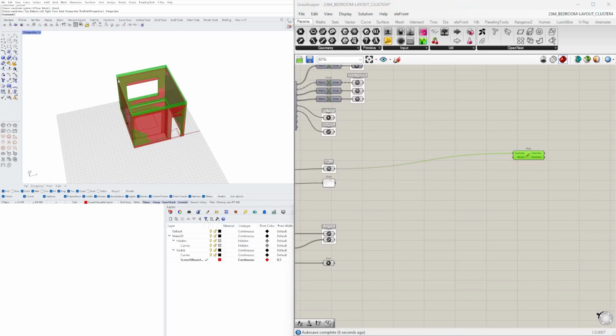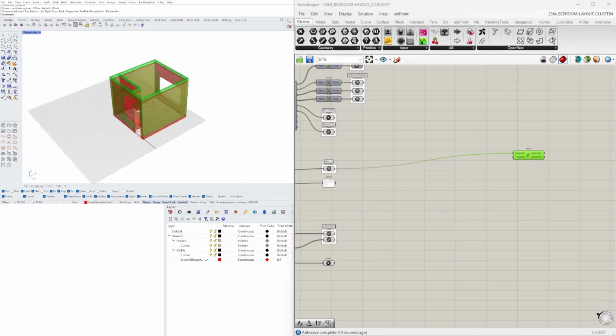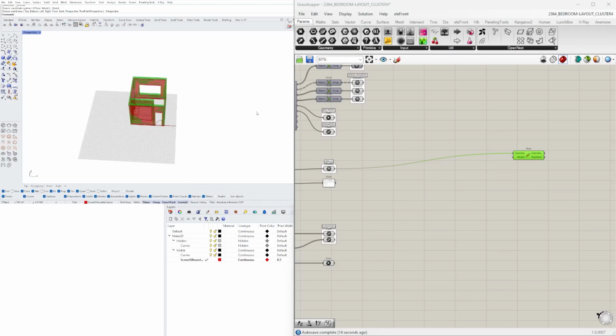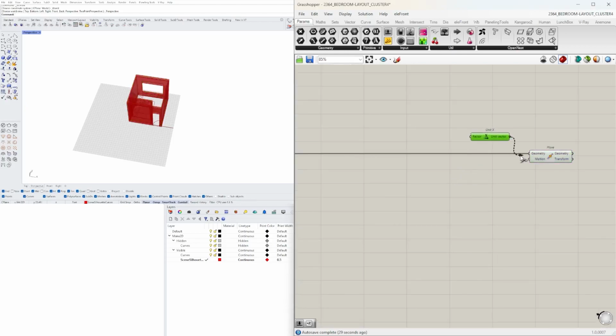And that's the reason why we want to array it in the X direction: the walls here and here are blank, which means that we can use it to array in one linear direction and then have egress and the doors not have any issues. Now we'll go here to motion, go to unit X, and now we need to figure out what's the size of this module, which we have in terms of a polyline.